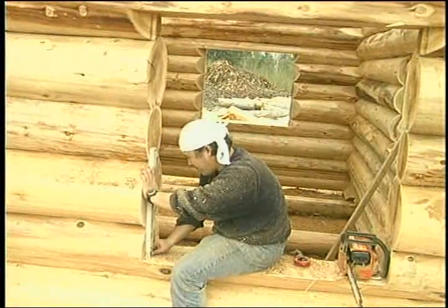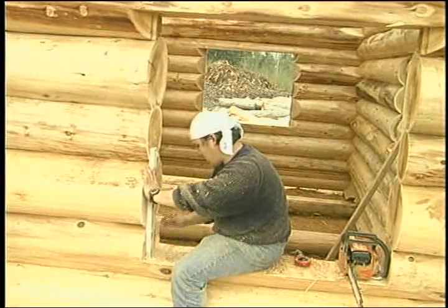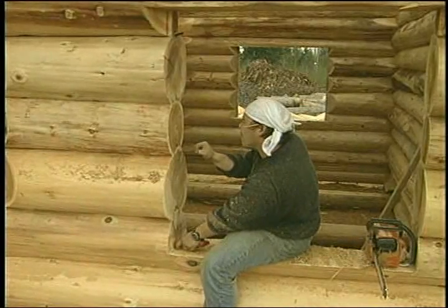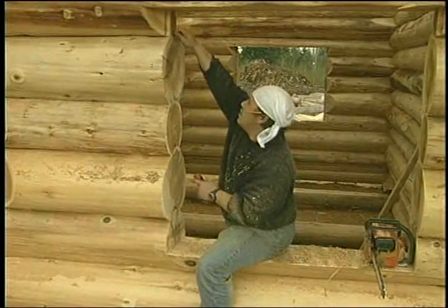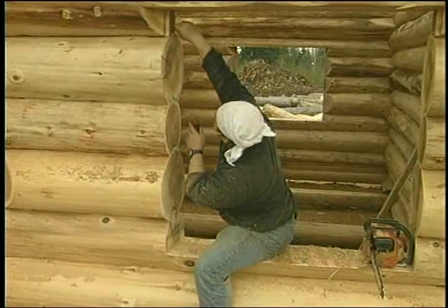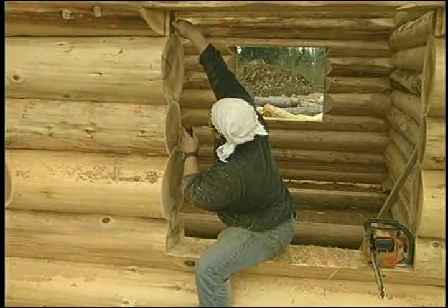It is customary to make this keyway 1 1/2 inches or 40 millimeters wide to fit a 2x4. Many other dimension materials could be used here, but get a good fit that is not too tight. If you have to drive the key piece in, it is too tight.